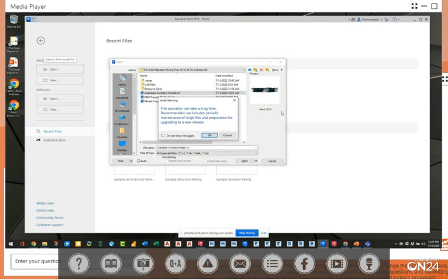So that's how corruption gets introduced into your projects, right? So it could be a bad thing, and how you avoid it is you have to upgrade them, save them all to the latest version, and run the audit while you're opening them up and saving them, and that's how you would bring in or update a family properly.